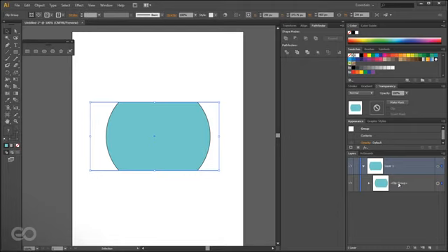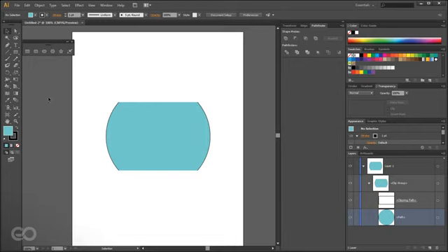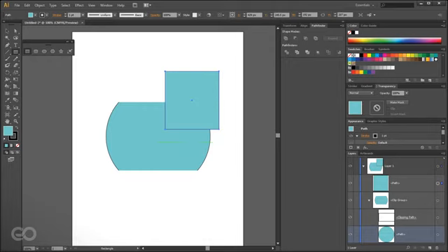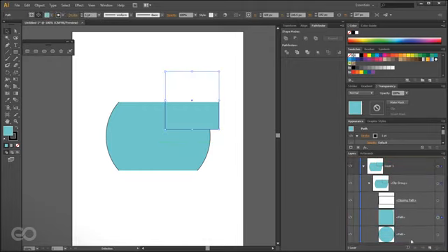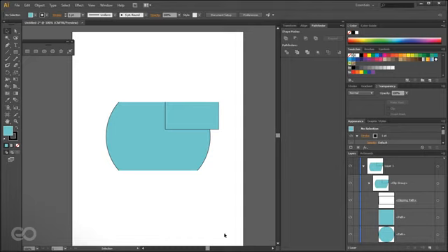And as you can see in the layers, it tells me I have a clip group, and you can see a clipping path exists, which is basically my actual rectangle, and my path exists, which is basically the actual path which I had. Now let us say I want to add an additional object into this clipping mask. I can go ahead, create any object I want, and I can directly drag it and put it below the clipping mask, and as you can see, it's being clipped too. So it's an easy way of clipping different objects or attributes just using this option.